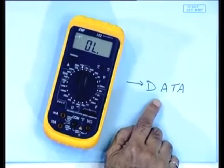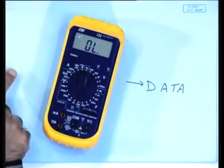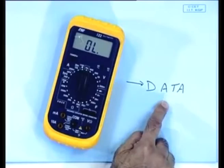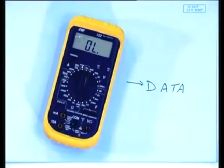Unfortunately, in most situations, the data is coming from the process into this system and then into the form of the data that we observe. Now, this system itself can introduce errors for us. And the idea of measurement system analysis is to take a look at the role played by the gauge and also the operator who is using the instrument in producing the data. And there are some methods that I'll be discussing today to make sure that, from the data that you have, you at least have a good estimate of how much error is being committed by the gauge and how much is committed by the individual, the operator.